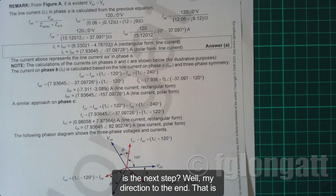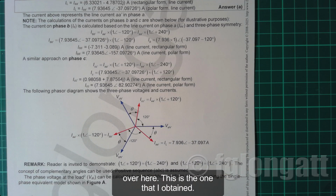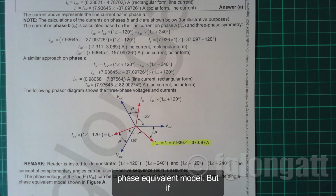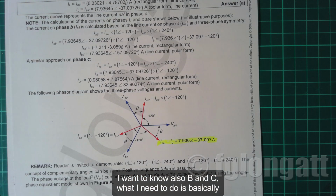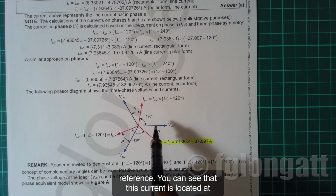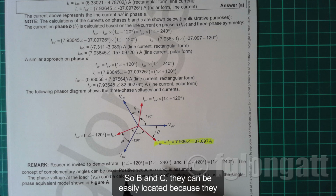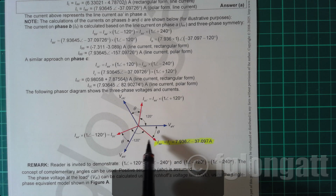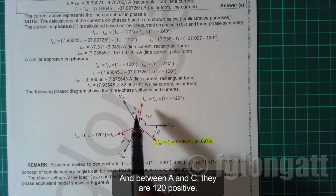So what is the next step? Well, my dear students, that is only for the phase A. This is the current that I obtained from the single phase equivalent model. But if I want to know also B and C, what I need to do is basically apply three-phase properties. As you can see, we assume that the voltage is the reference. You can see that this current is located at minus 37 degrees. So B and C can be easily located because they are 120 degrees apart. In this case, it is minus 120 degrees between A and B, and between A and C, they are 120 positive.